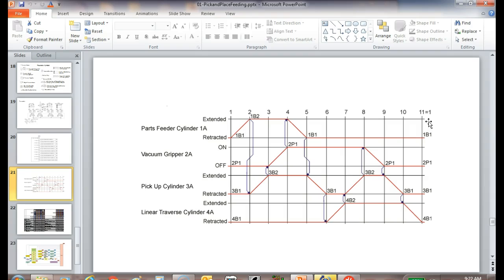So on number 4 galvanized line, we had the feed in, right? Then we had the welder that welded the strip together. Then we had the looper cars. We had the cleaning section where they dipped it and ran it through all those acids to make sure there was no goop on it. Then we had the preheat, then the coating section, then the cooling section or the tempering section. So every one of those was divided into different sections.